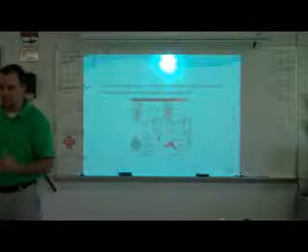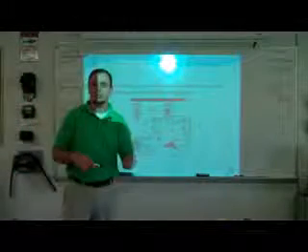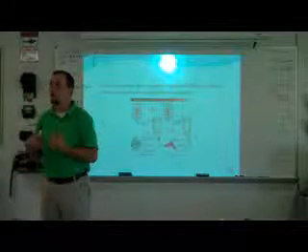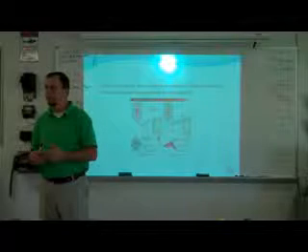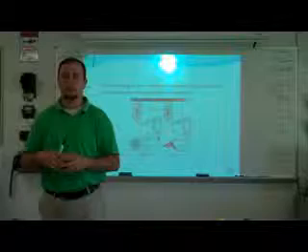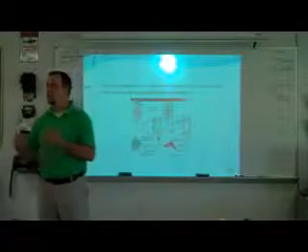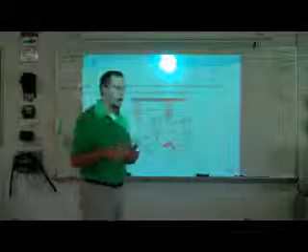It started pulling more and more amps, up to 17 amps. All of a sudden it started tripping my breaker because I was pulling overcurrent. I was overloading the circuit. So I had to take it out, clean it out, put it back together, and it went back to pulling 14 amps. It ran fine until it became starved for air.